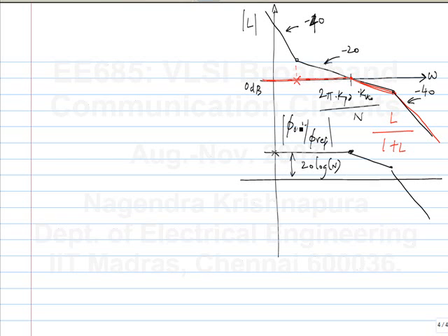If you delay the input by a certain amount, the output will get delayed by the same amount, which corresponds to n times larger phase when compared to the smaller period at the output. Also, it says that the output frequency is n times the input frequency. Okay, so that was pretty simple. The bottom line is, this is the bandwidth of the PLL.